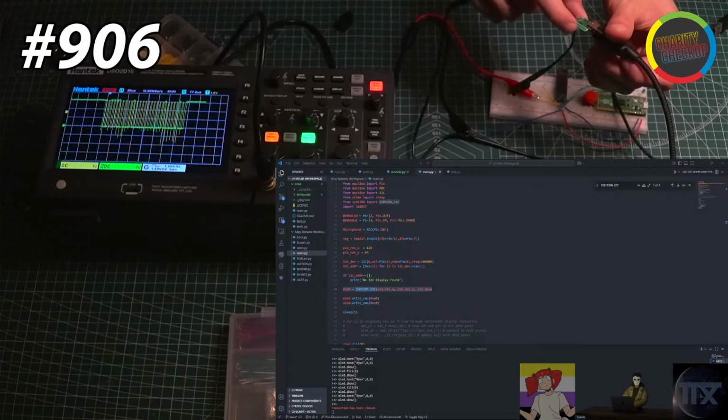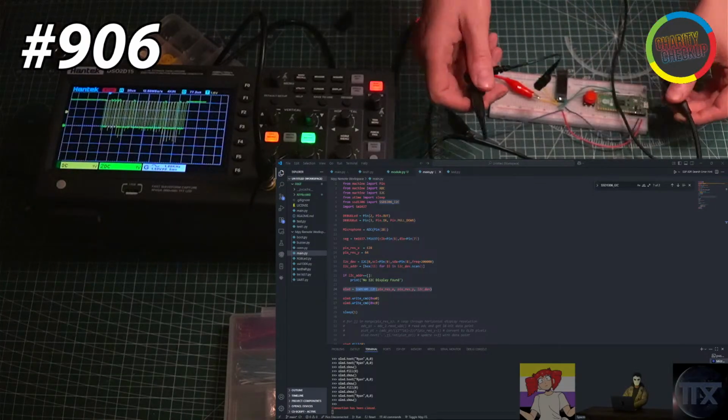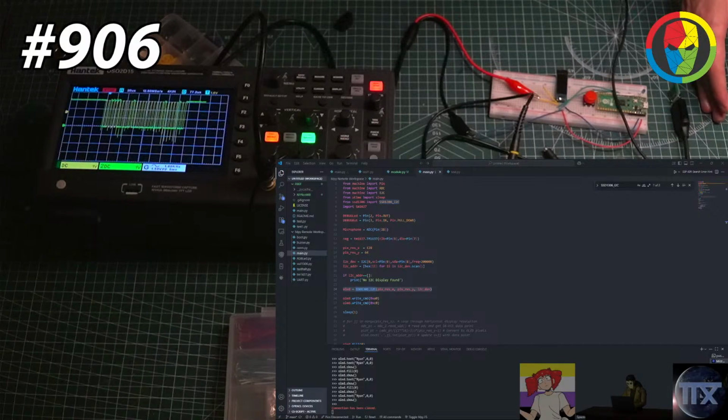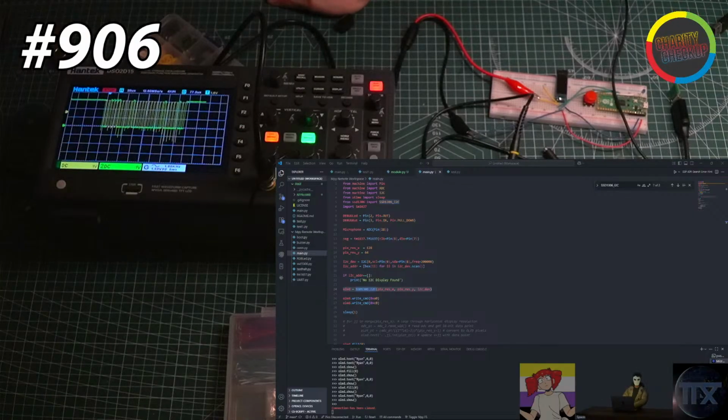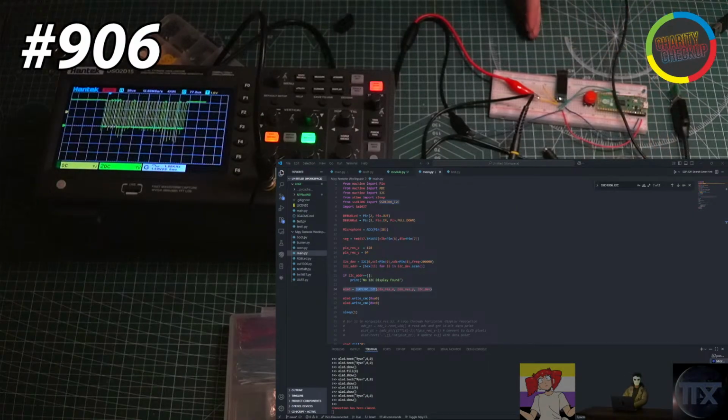Okay, so on the module, I am getting ground, V bus, D minus, D plus. Ground and V bus are obvious. The question remains, which one is D plus and which is D minus? Those are your two data lines. RX and TX. D plus could either mean sending data there or sending data from there. I don't know if you get what I mean. Like D plus could mean that's where the device is sending data from.